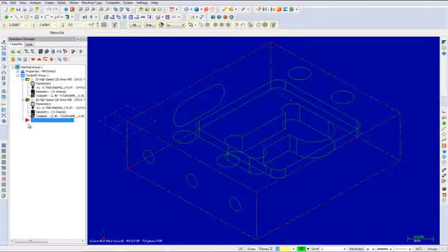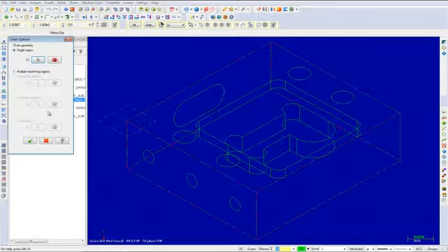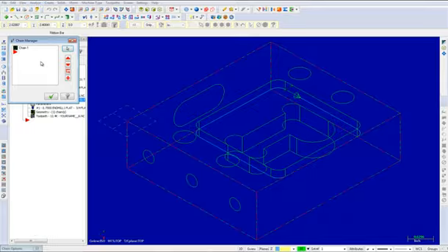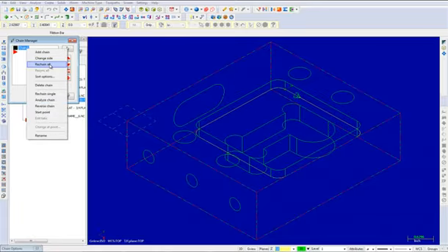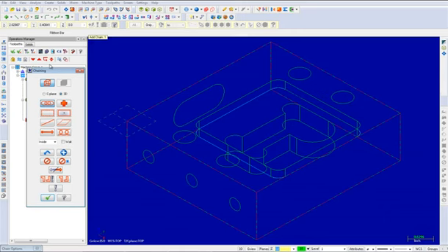In operation number 2, pick the geometry as shown. Now click the Select button. When the Chain Manager appears, select Chain 1. Right-click and pick the option to rechain all. When the chaining dialog box appears, choose the C-plane. Now select the bottom of the pocket as shown.